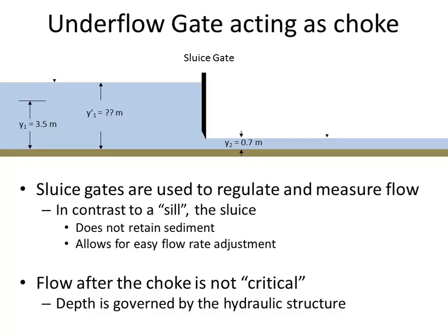When we start lowering the gate, the water won't begin to rise the second that gate hits the surface. It might be that there is enough specific energy to begin with, that the water can simply accelerate under the gate and make it out without any kind of choking.